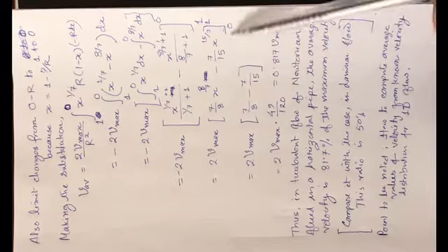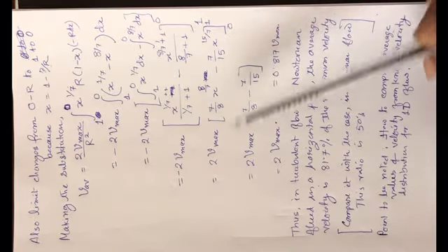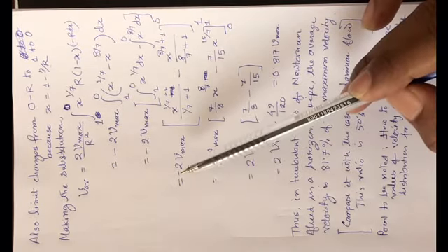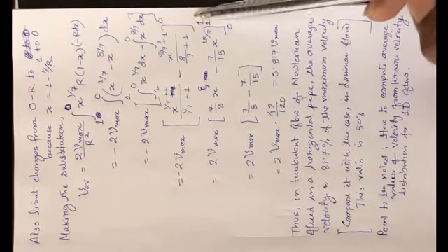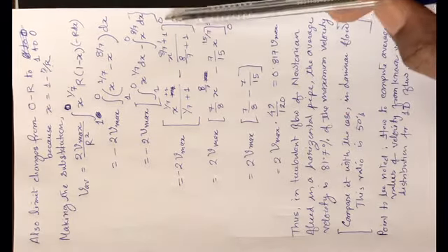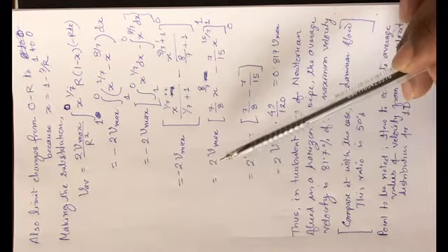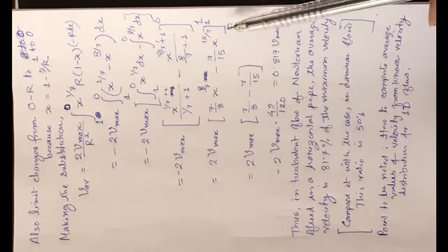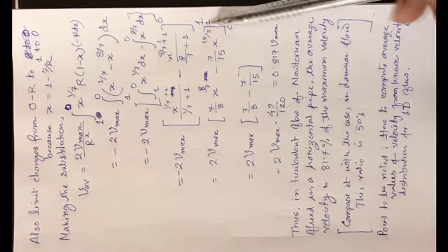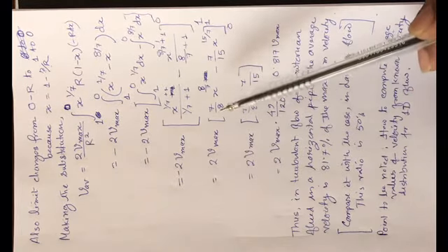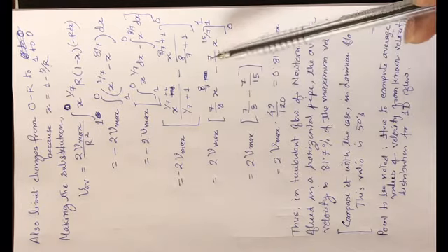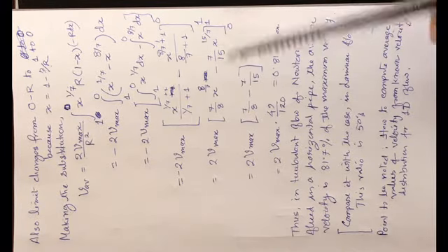Now this minus sign was there, so we want to eliminate it, and therefore we have changed the limit. Earlier it was from 1 to 0, and when we remove the minus sign, the limit is now 0 to 1. So 2 into Vmax, 7 by 8 x to the power 8 by 7 minus 7 by 15 x to the power 15 by 7.